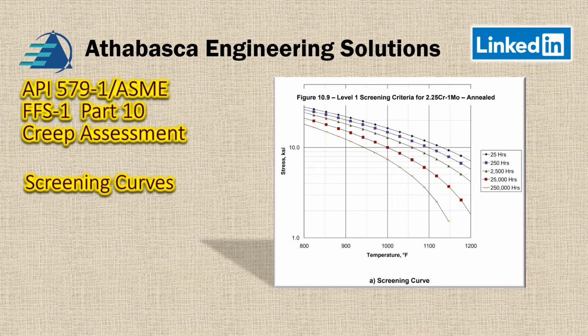So we determined earlier that our stress was 4 KSI, and our long-term operating life without excursion is shown here. We can see that we're over here on our curve, so that means we're somewhere over here for case 1. And so it gives you an idea that you're somewhere between, to say, 125,000 hours approximately left to go on your unit if there was no excursion cases. So that tells you that your tubes were well underway to the end of life anyways before this excursion happened. It determines your value for your unit.